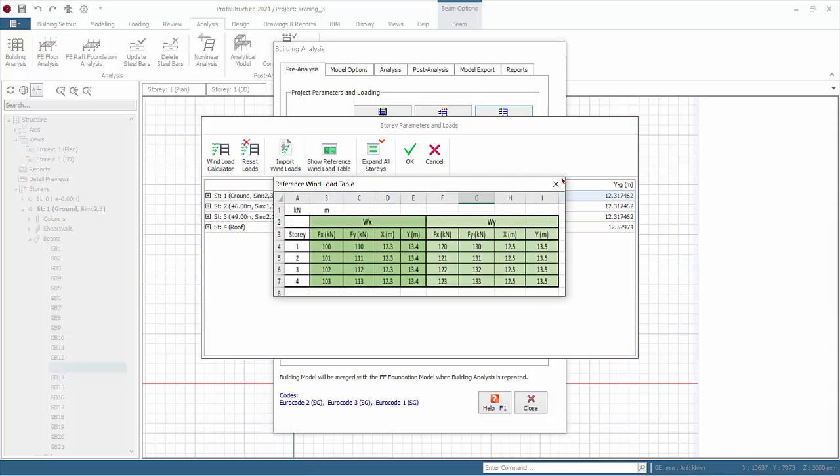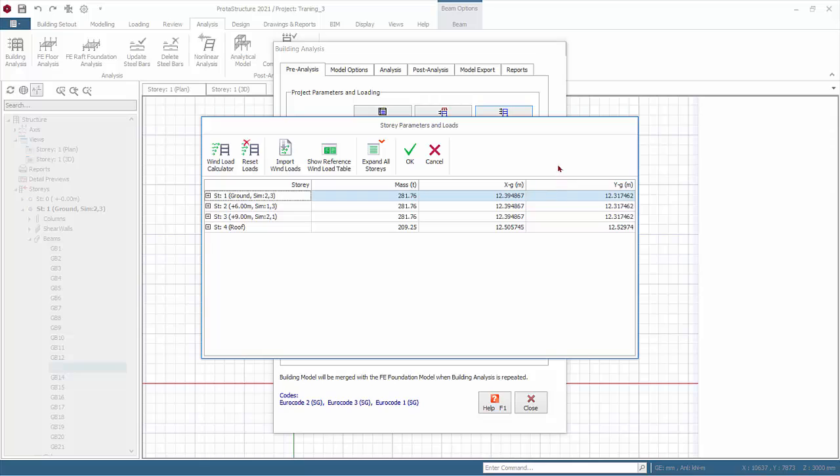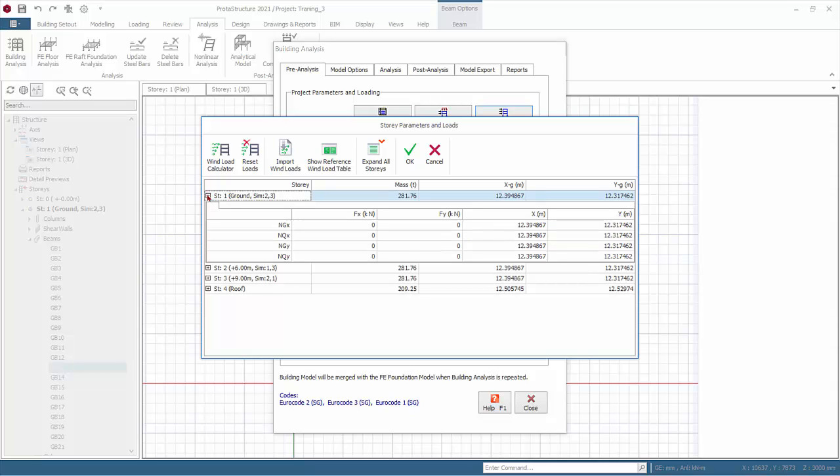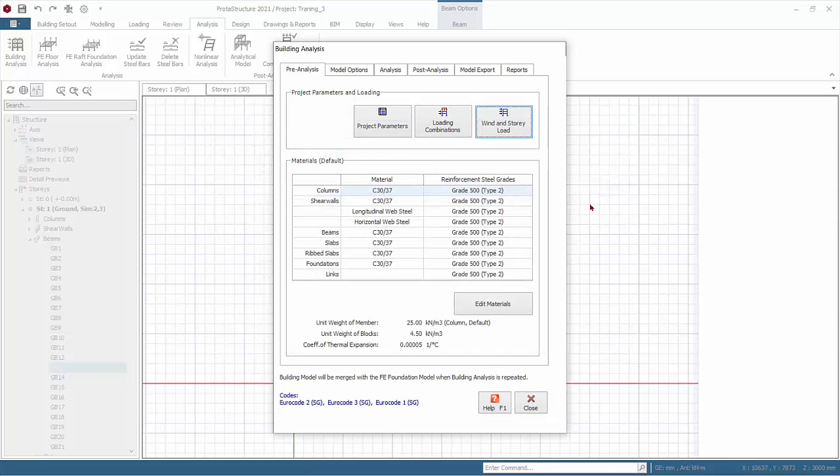In the table below, you can check and, or enter the lateral load values, for each story. Click on the plus sign to expand. The notional or equivalent horizontal load are shown. Currently the magnitude of the forces are 0, these values can only be calculated and shown after the analysis. Hence come back and check these values after the analysis. The x and y columns are coordinates of the application of the force, which is also the center of the floor diaphragm. Click Cancel to exit this dialog.